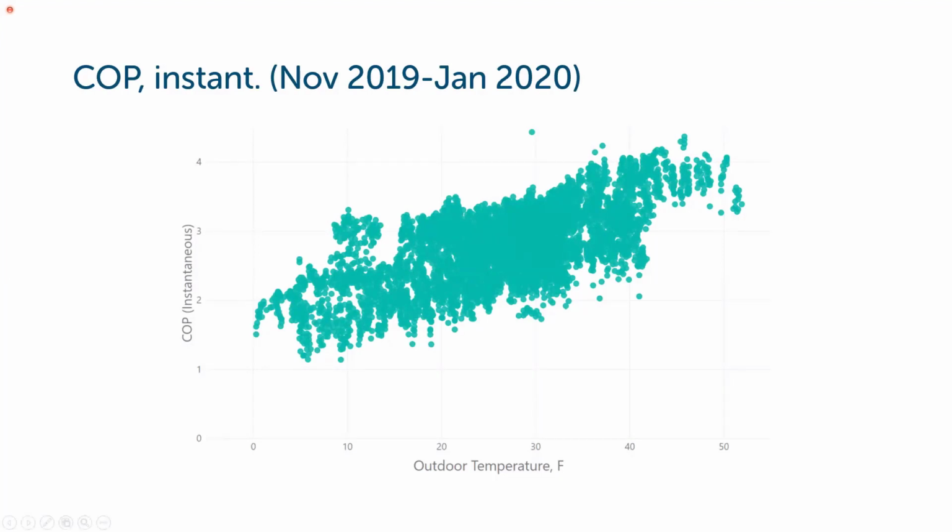Most of the air-to-water heat pump equipment available on the market right now is rated at about a 2 COP at 0 degree outdoor temperature in that range. So this is actual monitored performance data from Brian's system. And you can see at 0 degrees, the coefficient of performance was definitely above 1, close to 2. So even at those low outdoor temperatures, and you can see the majority of the heating season is in this range, 20 to 30 degrees.